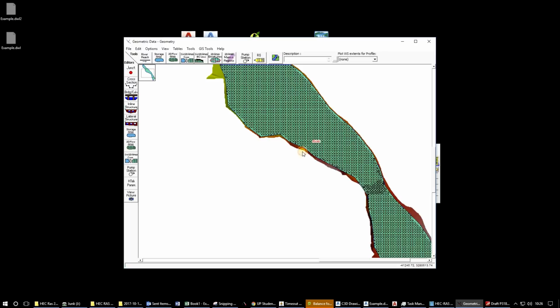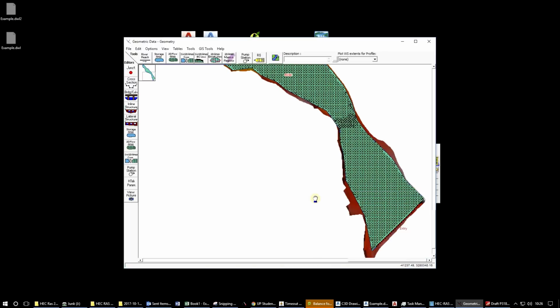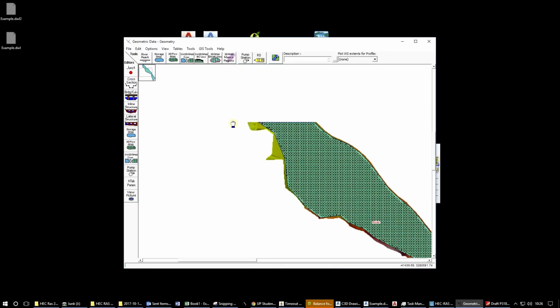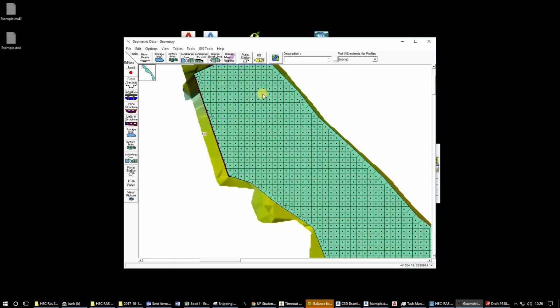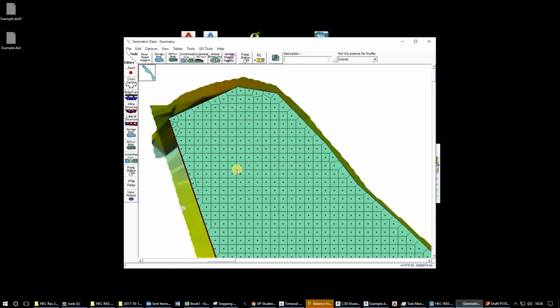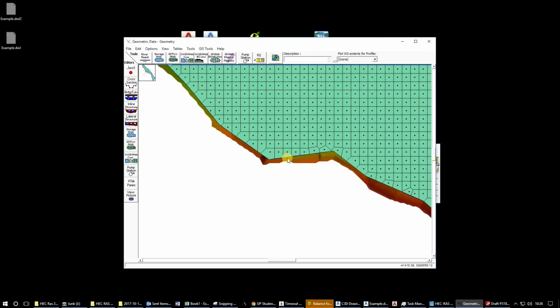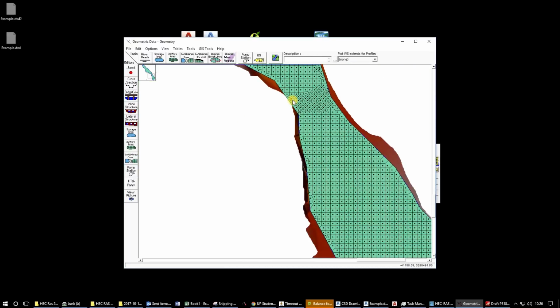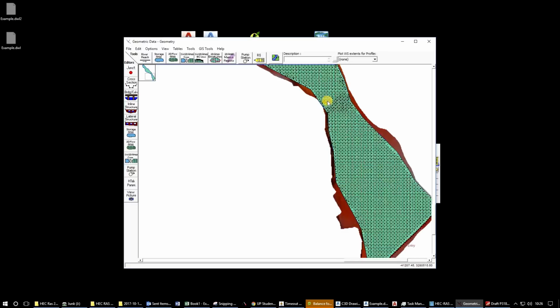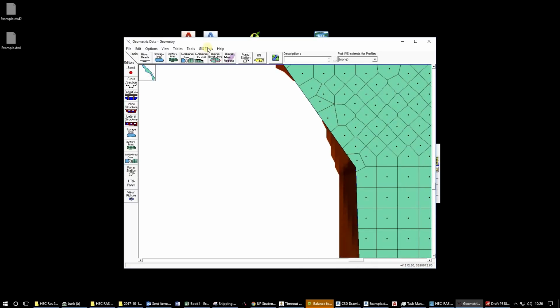2D mesh, like we saw, we didn't get any red node, so there's no specific mesh element that is causing the problem, but we know about this issue that we caused where the 2D area actually goes outside the terrain. So let's modify that and see if that solves the problem.